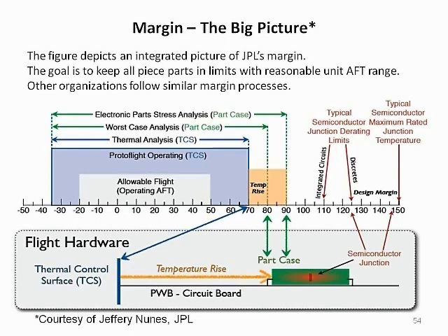Inside the unit, there will be temperature rise from the baseplate up to the point where the piece part is mounted on the circuit board, as determined by worst-case analysis. An electronic part stress analysis is conducted at a temperature 10 degrees C above this level. All predicted piece part junctions must stay below their derated design temperature limits.